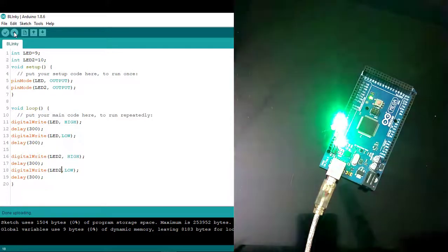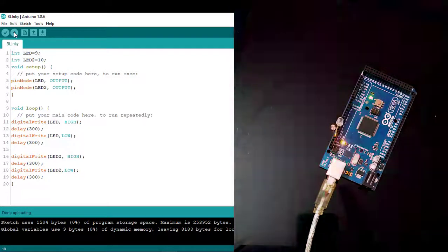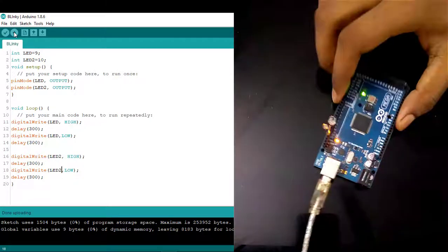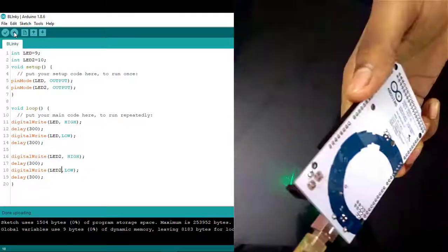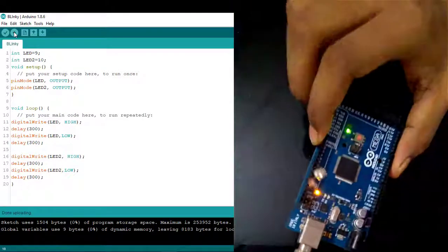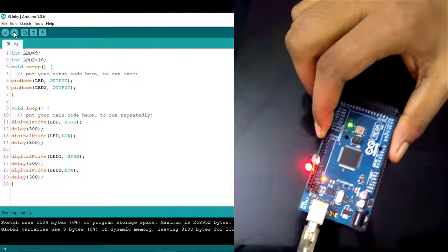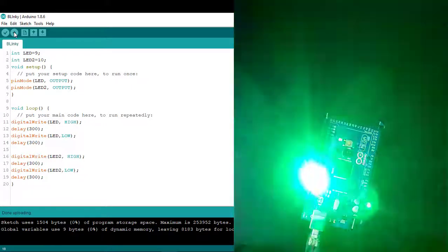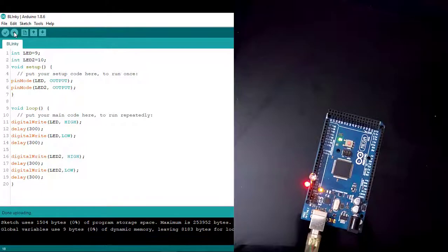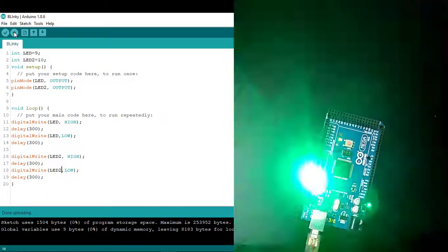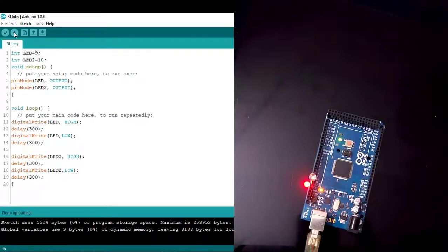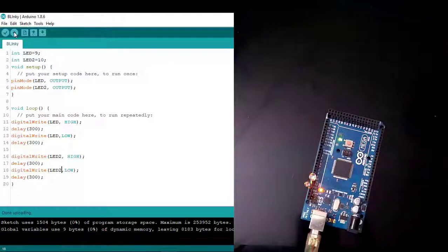Now there are some important precautions that you must know. These types of Arduino boards are very electrosensitive. That means these parts should not be touched with fingers or anything electrostatic. So we always have to maintain this, or else your microcontroller can blow up, and these are important things. You can see how easy these topics are. You can do all of it as it is going, and you can use more sensors. You can add more sensors and actuators to get things done.